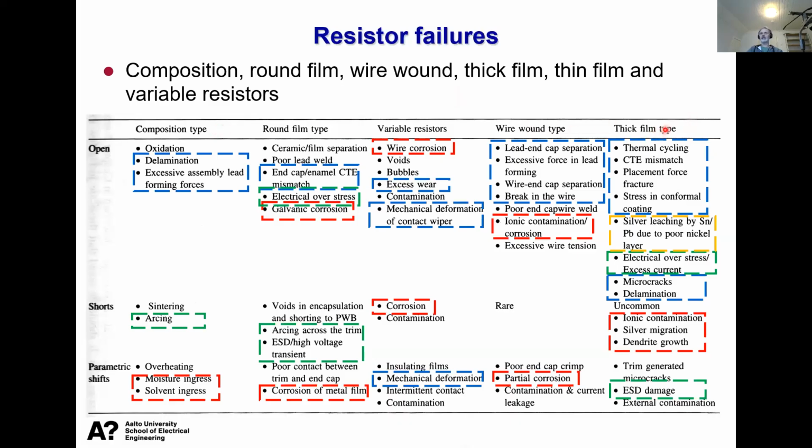What we are missing here is the thin film type resistors, which are maybe the most common or second most common in modern products. Of course, for example in the Galaxy Watch, most of the resistors are this kind of thick film type, one could assume. Then with some other applications where one needs higher currents, higher voltages, higher powers, and the space is not that limited, you need a larger variety of, for example, resistivity values, then you can have different types of resistors still.